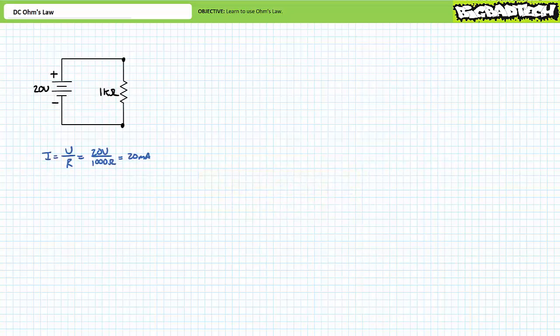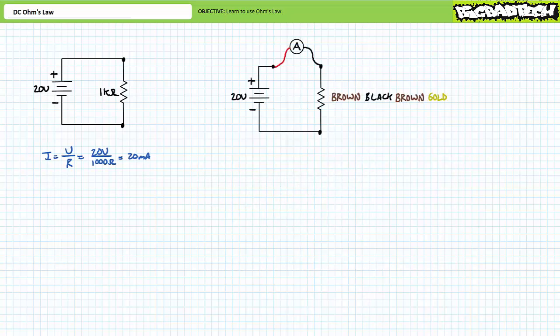Current is voltage over resistance. An application of Ohm's Law demonstrates we should anticipate 20 milliamperes of current. Let's say we build this circuit, and as soon as we turn on the power supply, current spikes to 200 milliamperes, and rather quickly, the resistor's paint job turns an ugly shade of brown, starts smoking, and is soon engulfed in flames. What's the problem?